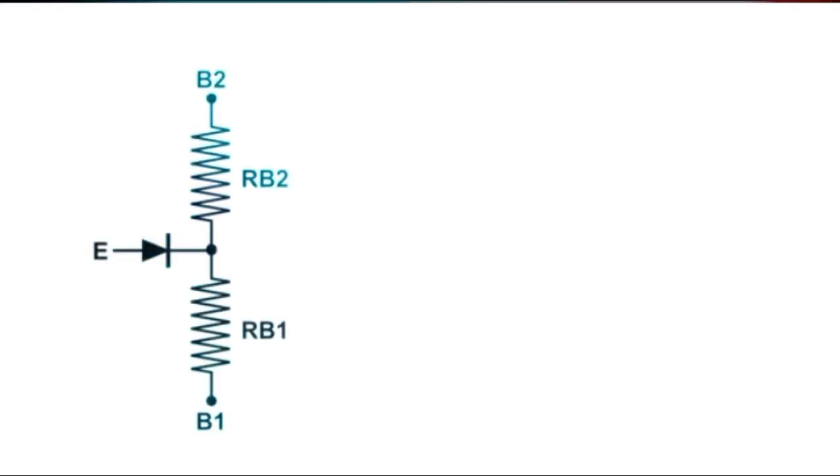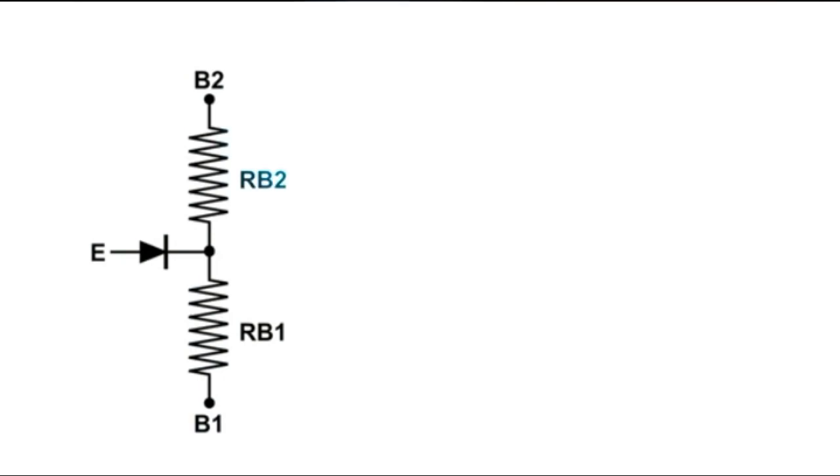According to the equivalent circuit you see, the N-type channel basically consists of 2 resistors RB1 and RB2 placed in series with an ideal diode, D, representing a PN junction and connected to the center of the resistors. This PN junction emitter is placed in a fixed position along the ohmic channel during the manufacturing process and cannot be changed.